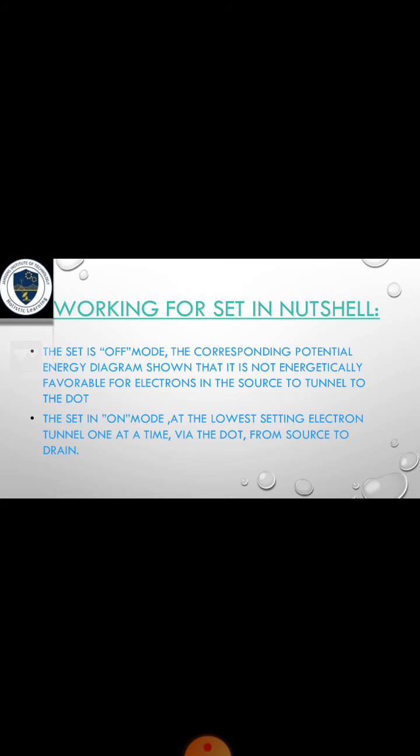Working of a SET in off mode. When the SET is in off mode, the corresponding potential energy diagram shows that it is not electronically favorable for an electron in the source to tunnel to the dot. Now the SET is in on mode.